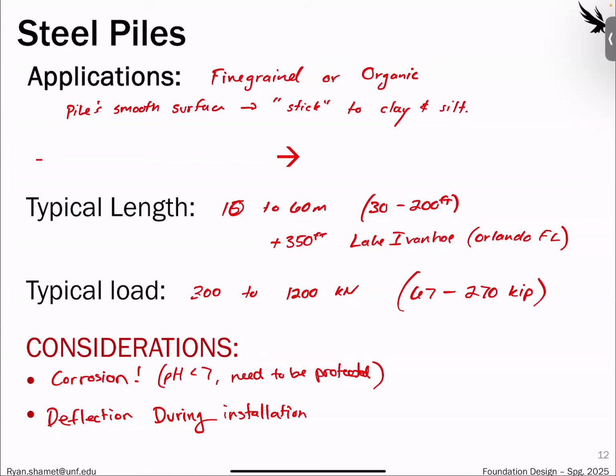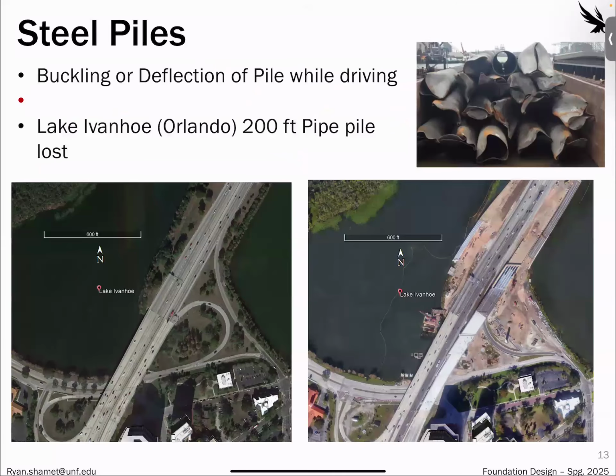If you're super fancy, you can put accelerometers on the piles, but then you're scrapping the accelerometer on the base, because it's buried underground. So if the client has a bunch of money and they want to insure it, you could put some sacrificial sensors underground. But that's one of the research areas to really test, because once the pile's underground, you can't see it, so that's a big thing.